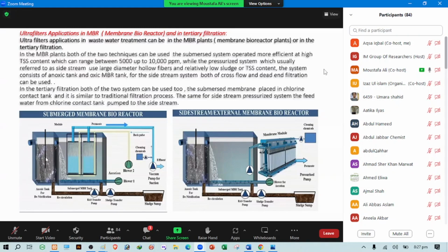In this step, let's say, here we have anoxic bacteria, here oxic bacteria. We have a set of air diffusers to supply dissolved oxygen. Dissolved oxygen is monitored to be between 1 to 3 ppm.